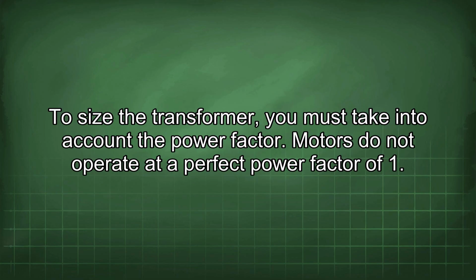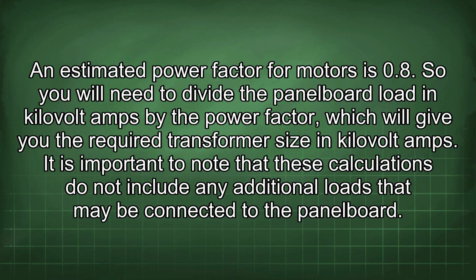To size the transformer, you must take into account the power factor. Motors do not operate at a perfect power factor of 1. An estimated power factor for motors is 0.8. So you will need to divide the panel board load in kilovolt amps by the power factor, which will give you the required transformer size in kilovolt amps.